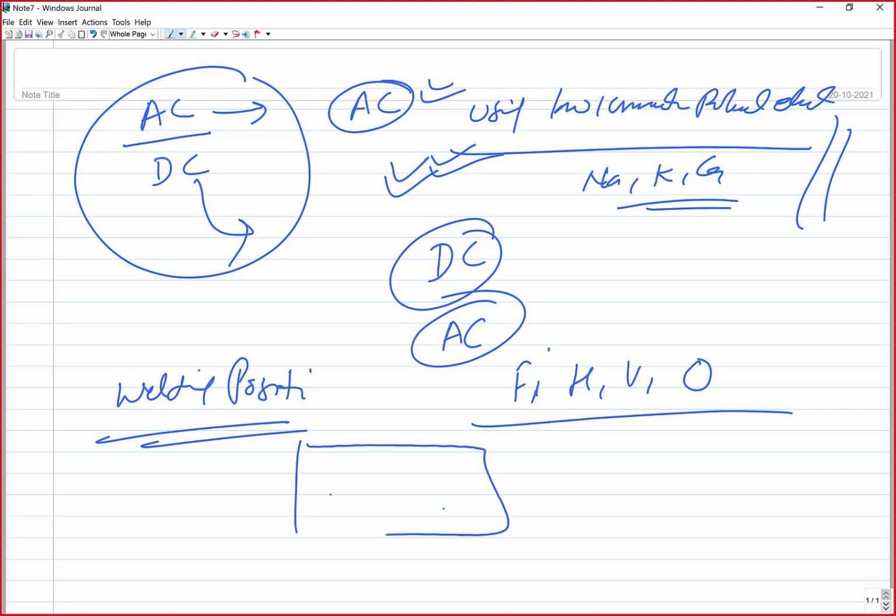In a flat welding position, the plates are in a horizontal position and the weld is simply made. There is no issue as such with generating high heat input in flat welding, because you can easily place the molten metal wherever it is desired.